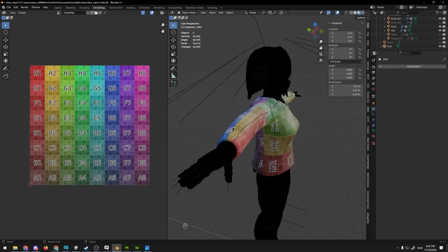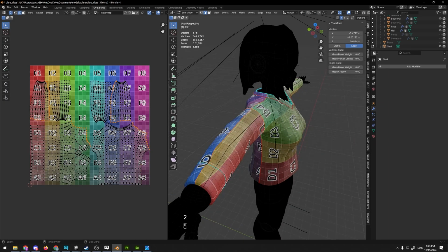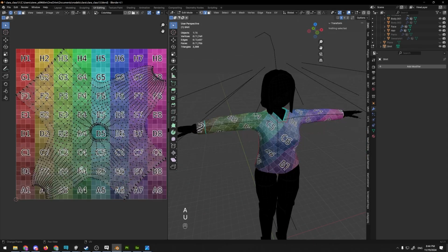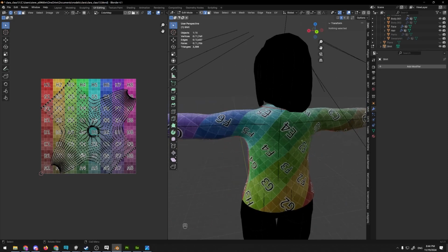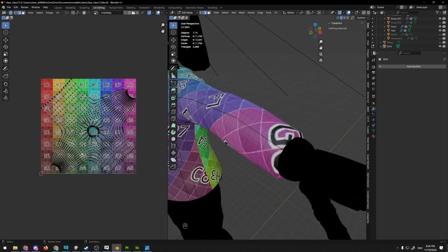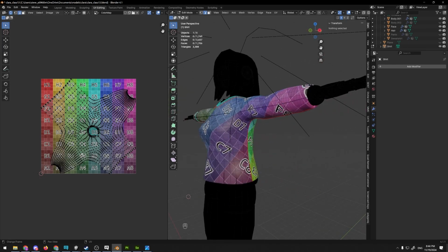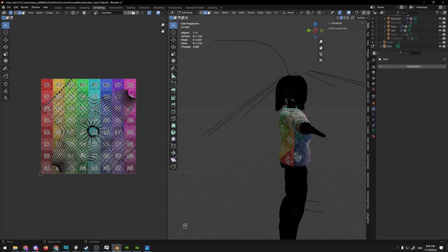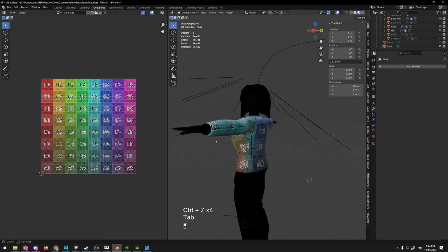If we go back to the version we had before and use this same texture, where I didn't have this seam or this seam or this seam, where I didn't have any of these, clear seam and unwrap, we go back to this image that we had before, or just a single island. You'll be able to see a lot of this stretching a little bit more apparently, especially on the sleeves. You see how these numbers are huge over here and they're much smaller over here, and it kind of doesn't look quite right. It's still not bad, all things considered. You could actually roll with this, it would work, but it's not good. So that's why we use multiple seams across our mesh to give us a more consistent view.